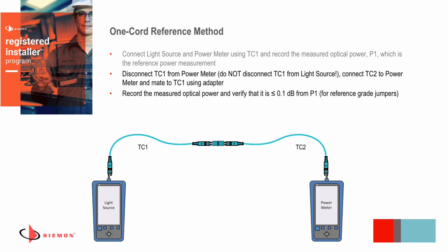Now, it's important to remember that in some cases the optical loss test sets have a reference button feature that skips this qualification step. So again, it's important to engage with your optical loss test set manufacturer and ensure their procedures match up, and they might have something that's a little bit simpler.